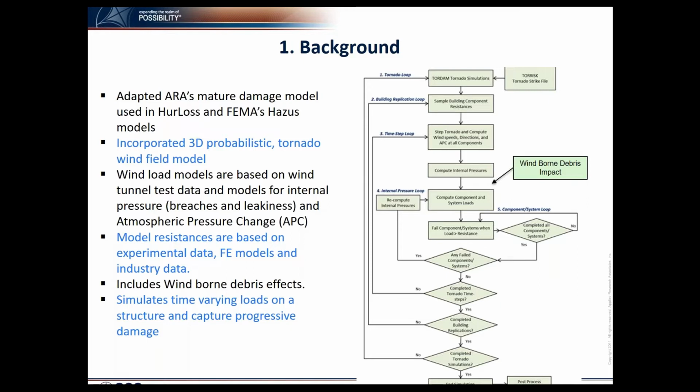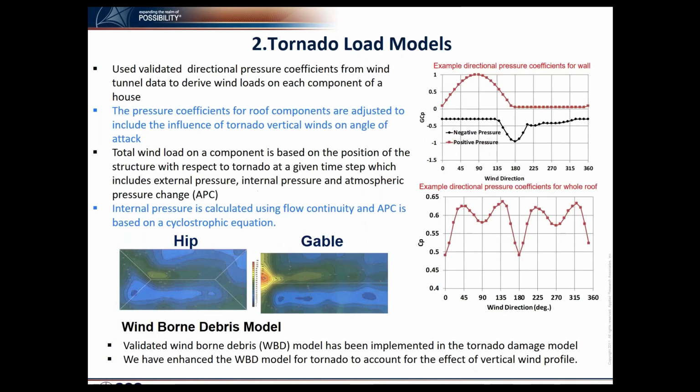So it's basically a load and resistance model. The loads are based on wind tunnel data, and the resistances come from the experimental results, finite element modeling, and some industry data. It also includes the windborne debris effect. Since it's a time stepping model, it simulates the time varying loads on the structure or building, and then captures progressive damage along the way.